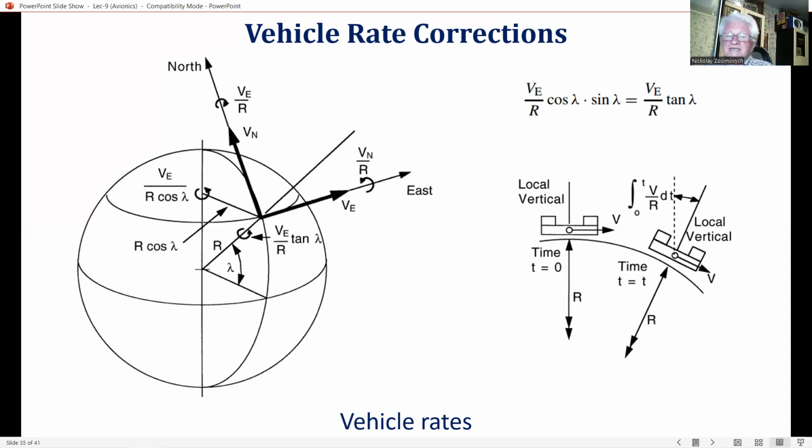The Doppler or air data derived velocity components would generally be combined with the inertially derived velocity components from the accelerometers, as will be explained a bit later. The use of very high accuracy gyros and accelerometers enables the velocity components to be derived directly from the accelerometers and fed back to correct the vertical reference so as to form a Schuler-tuned system, and this is explained later.